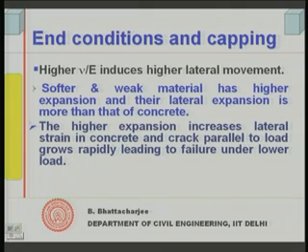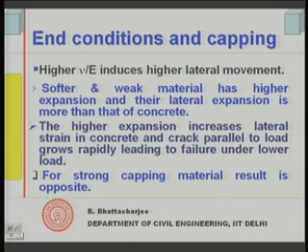So, if this value is higher, it would mean that the concrete would fail under a lower load, whereas if the capping material is strong, then this will result in higher strength of the concrete. A strong capping material has a low Poisson's ratio divided by E, that is, high stiffness; a high E does not want to deform, and a low Poisson's ratio does not transfer too much stress along the transverse direction.